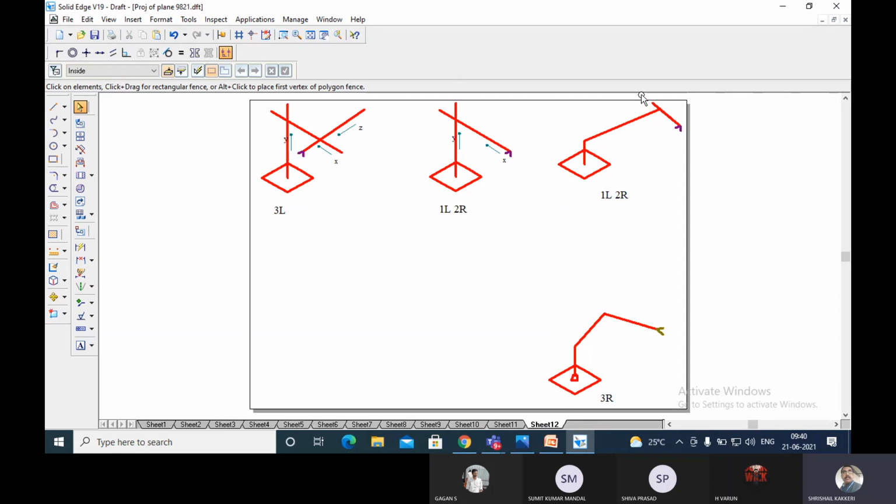And let us come to this. It will be a spherical, or segment of a sphere, and the mechanical stability will not be as good as these two. So it requires a little better controller, because two rotational joints are increased. What kind of application will you be using it for? This can do all these operations. Pick and place you can do, and it can do simple welding and spraying operations. Along with that, it can perform assembly operations, and complicated welding and painting operations it can do. So almost all industrial robots will have these three types.